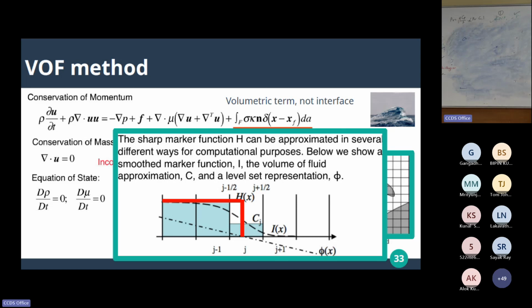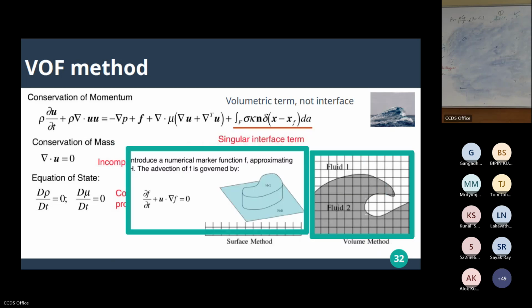But when you are using any kind of multi-phase flow, capturing such a sharp discontinuity is not possible, even under low Mach numbers. Maybe sometime back, you must have solved compressible flows. The whole point there is capturing the shock, a very sharp kind of thing. But multi-phase flows, by definition, always have these so-called discontinuities or shocks, even at low velocities. Can we really capture that? How do we solve this equation?